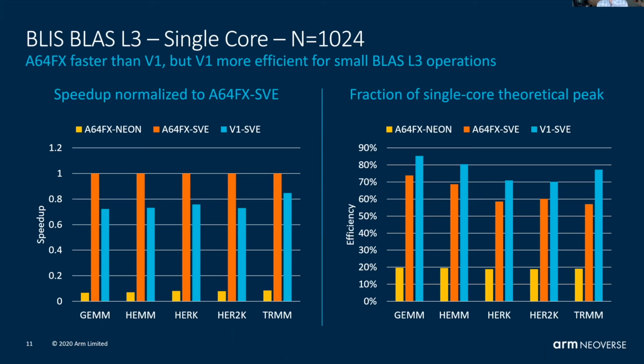And the ability for the code that was developed on the A64FX to port forward to the V1. It is very encouraging, however, that we're seeing good performance and great efficiency without any code modification. This speaks very well to the idea that SVE code can move forward through architectures even as the vector bit width in the hardware implementation of the SVE unit changes.